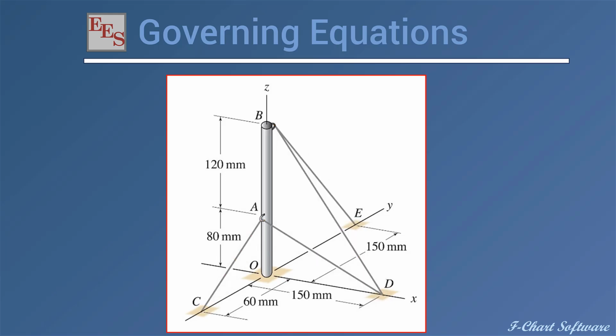And so we know the directions of the forces, and we know the magnitudes of the forces, and it's a pretty straightforward thing then to calculate the cross product of the position vector that defines the location of the force relative to the point and the force itself, and that gives you the moments, which are vectors. So we'll do that, and then we'll also visualize these moments, which I think is really nice because it lets us understand what the moment vector really means.